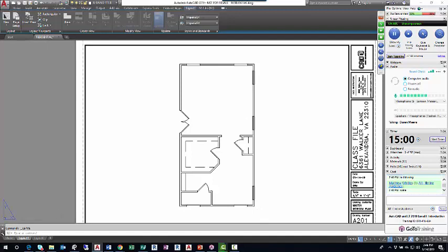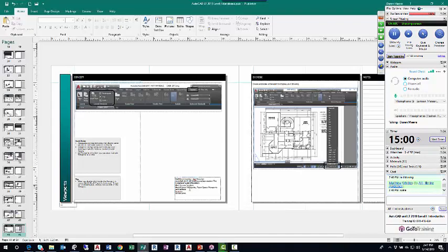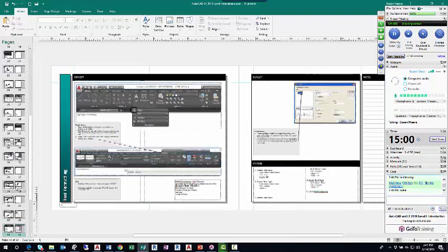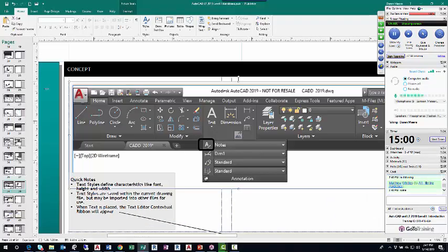And I'm going to do this from model space. I'll click on the model tab. There we go. So in the model tab, I'm backtracking now to page 338, formatting text. There's a little dialog box that we need to get into to format the text. And the way we access it, I'm going to zoom in, is we'll go to the Home tab of the ribbon. We'll expand the annotation panel, and we'll click on this button here, this little A with a paintbrush in the annotation panel.